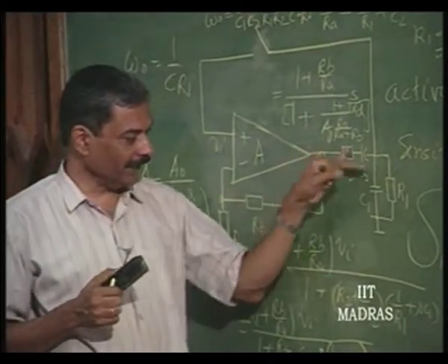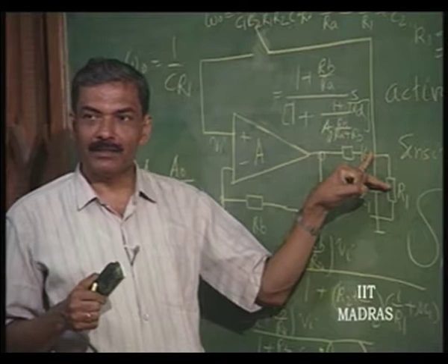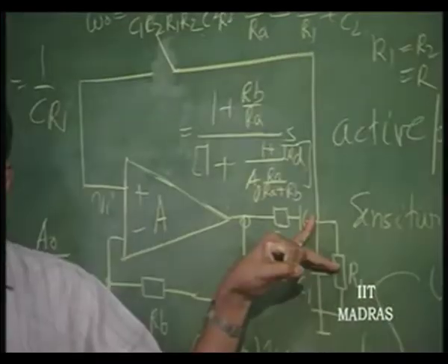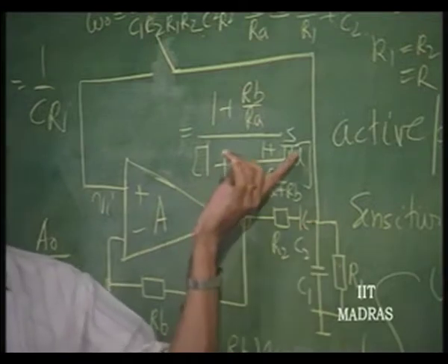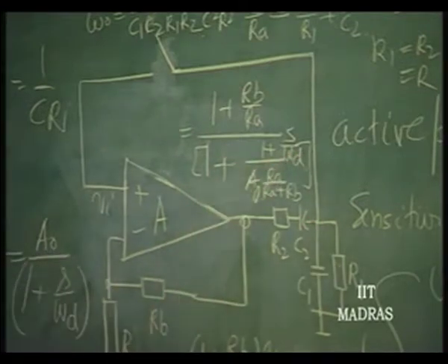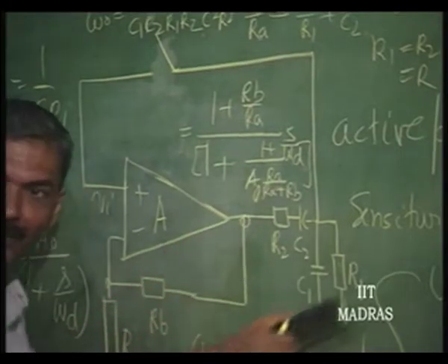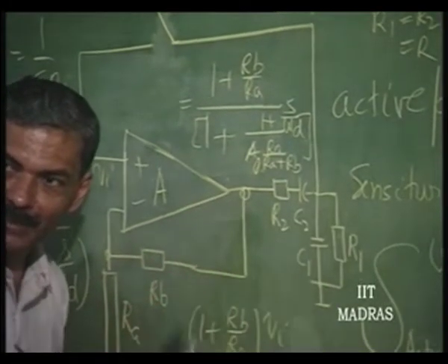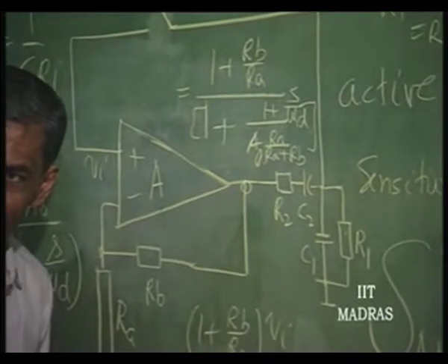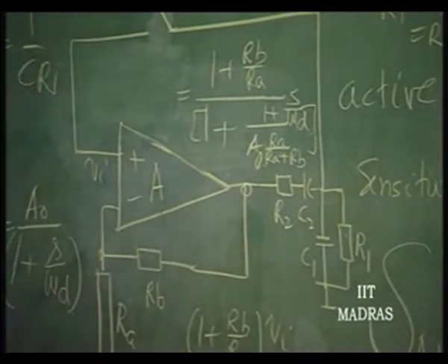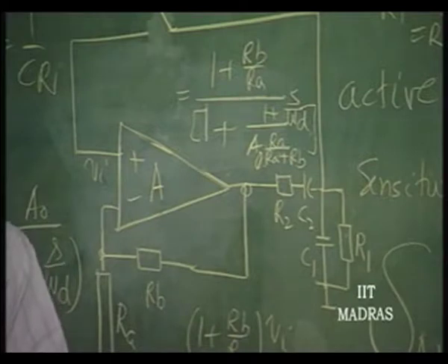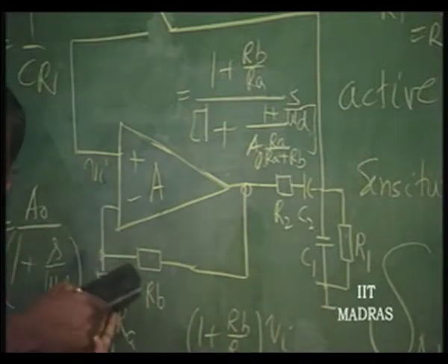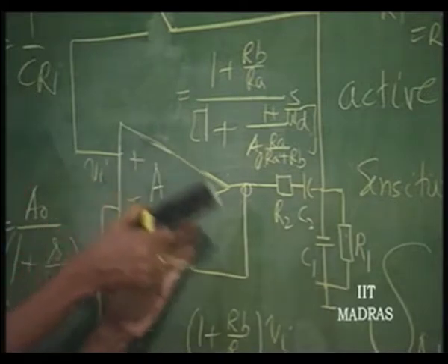So, the phase shift of this should be such that it will give you a phase lead, that means it will be different from omega naught. How much it is going to be different depends upon this phase shift here, right. So, we have to study the phase variation of this passive network Z1 by Z1 plus Z2 in order to say how much it should differ from omega naught in order to give a phase contribution of 1 radian, phase lead, so that the phase lag by the active device is compensated for by the phase lead here.